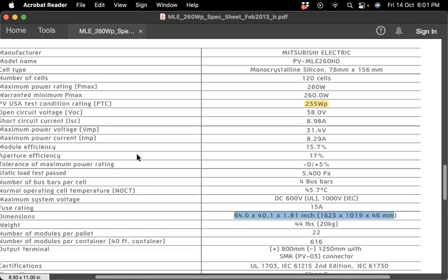But generally, we have to agree that the operation of solar cells is highly influenced by environmental conditions. All these good numbers listed in this table, like this 260 watts, this 8.2 ampere or 31.4 voltage, all these parameters are listed considering what we can call standardized conditions.